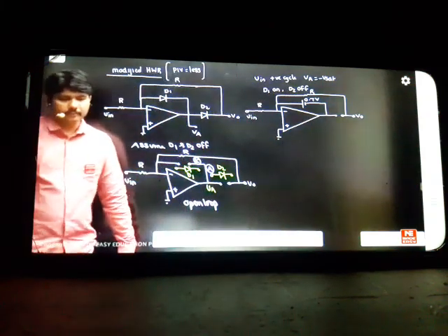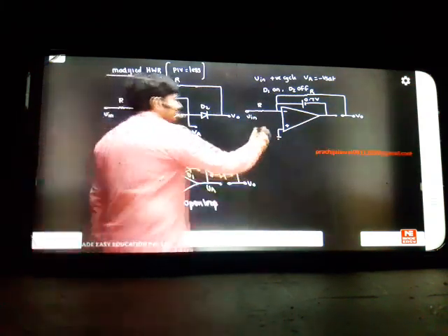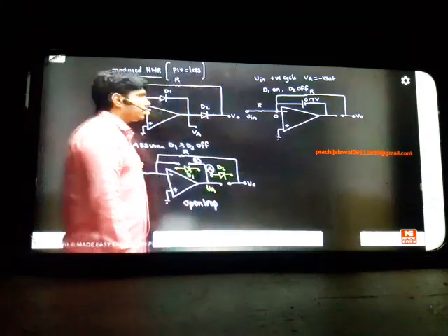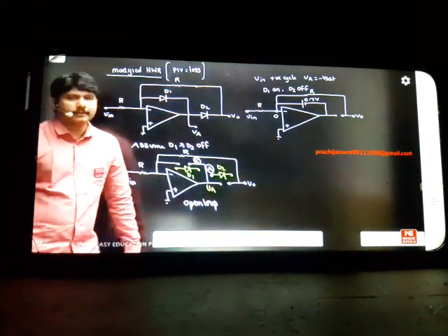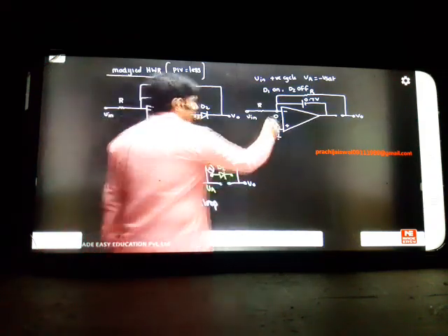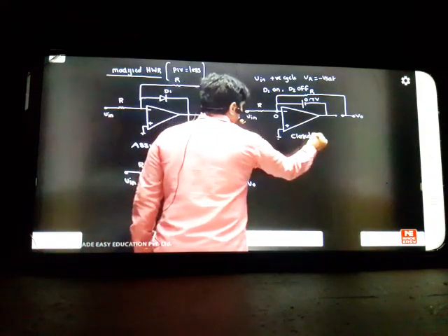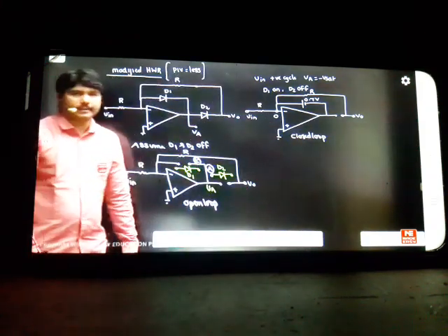One diode is on, one diode is off. So what will happen is, this is virtual ground, we can take it as 0, because it is in closed loop. It may be open at the final stage of feedback, but it is closed here, in the inside closed loop itself. So it's a closed loop, it's not open loop. So virtual ground you can apply, it's a closed loop, first confirmation. Maybe one feedback loop is open, but one feedback loop is not open. So the diode has closed it. So it's a closed loop.